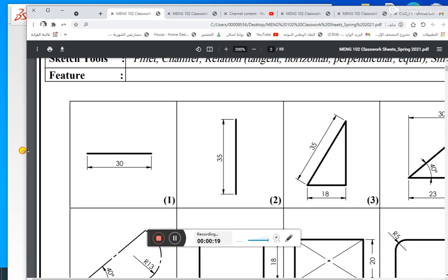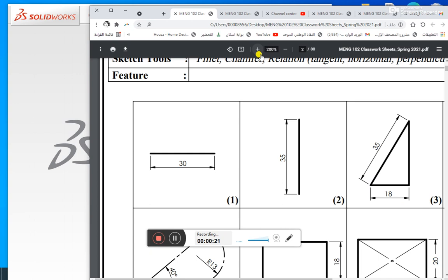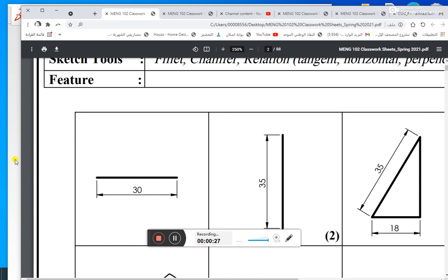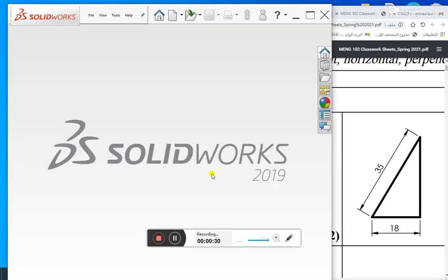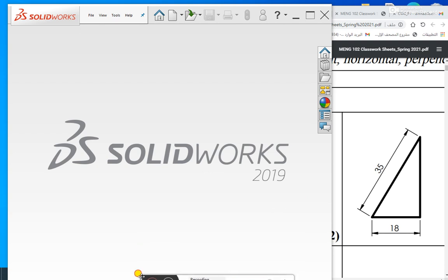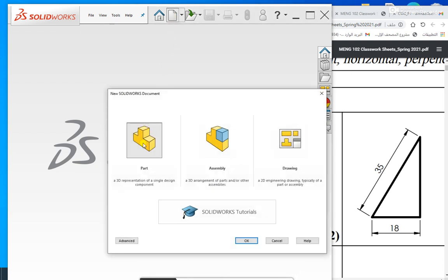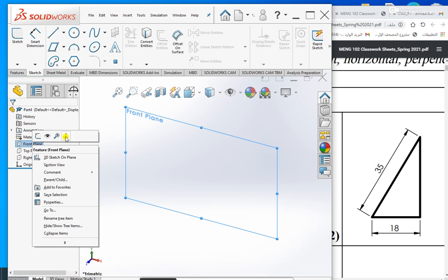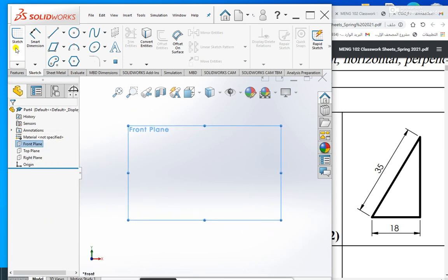Okay, so we just push this window a little bit to the right and we'll maximize it. Zoom in. Then click on the SolidWorks software here. The same steps: new part, then front plane, right click, normal to, then activate sketch to add the origin point. Then where should we start and what is the tool that we use here?